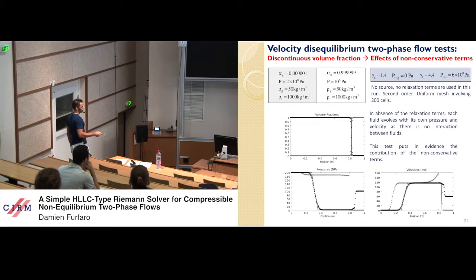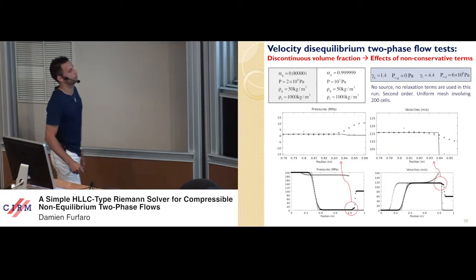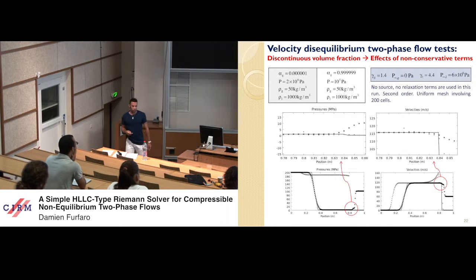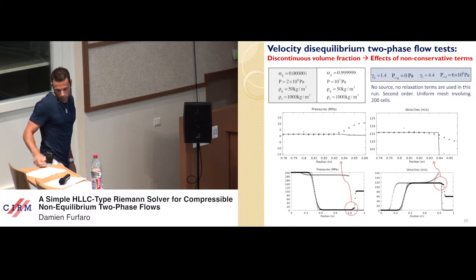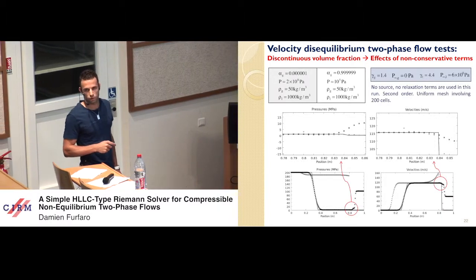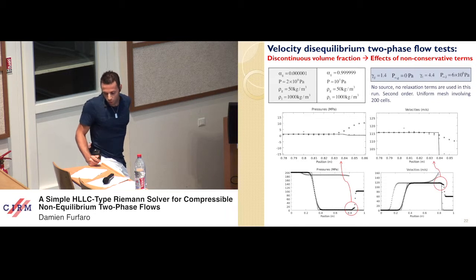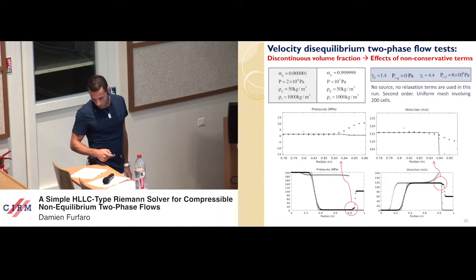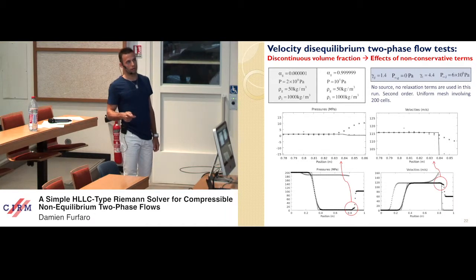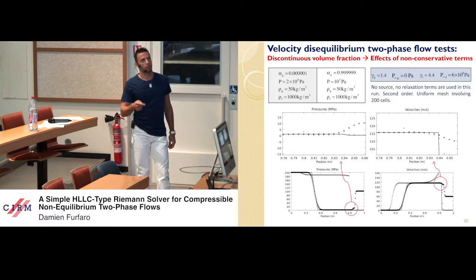The liquid is also accelerated by the shock wave in its negligible volume. But the most important point is that interfacial conditions are perfectly matched. Here we can see the interfacial condition for pressure and for velocity. So these results show that the numerical method is able to deal with multiphase mixture in non-equilibrium velocity, as well as interface problems separating pure or nearly pure materials. Interface conditions are matched as a consequence of non-conservative terms and do not need relaxation ones, which are absent in this context.